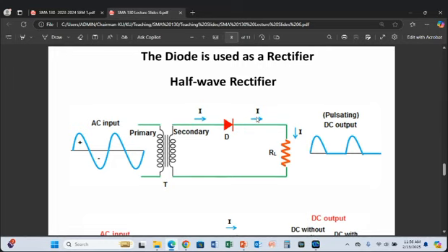So we call this a half wave rectifier. The current is positive, positive, and we say it is flowing in the same direction. You can see current flowing in the same direction through the resistor, but in the transformer, it is changing direction. So here we have AC input, we get DC output. Therefore, a rectifier changes AC to DC.